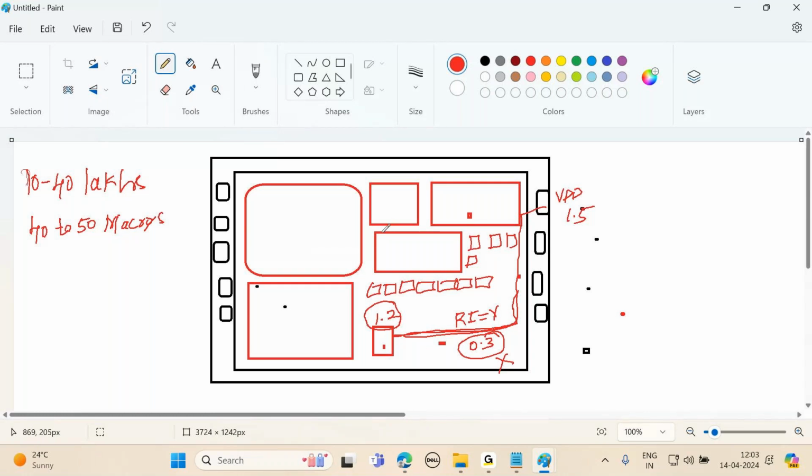Right? So now my question is whether we are going to draw the layout, as physical design engineers. This is a layout of an AND gate. Have I drawn the layout of an AND gate in any of the flow here? No, I am not going to draw the layout. Physical design engineers do not draw the layout. It is drawn by the layout team. That layout team is going to give it to us in the form of a file called the LEF file, Layout Exchange Format file. This file has layout information of all the standard cells.